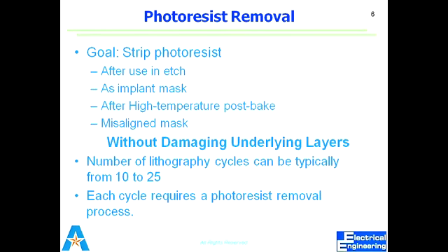Okay, as discussed in the lab as well, regarding the piranha clean, piranha clean is mostly used for removing the photoresist residues, if you remember. The strips of photoresist need to be cleaned; this is one of the very critical steps when you are cleaning. You need to make sure that there are no photoresist residues, because when you are fabricating a device, it may happen that you are spinning the photoresist, you're patterning your film, and again you need to pattern another layer of some other material. So you spin the photoresist again, and it may happen again and again.